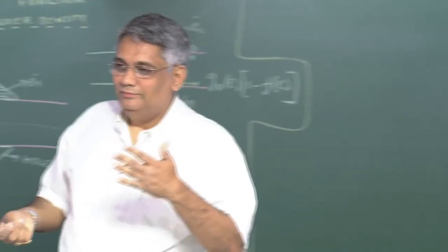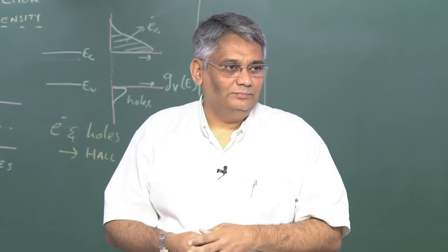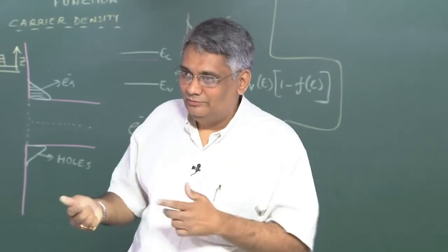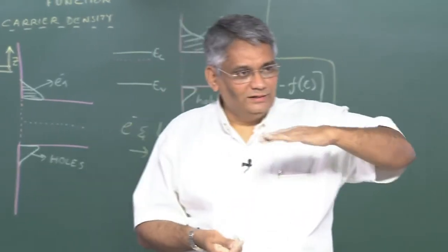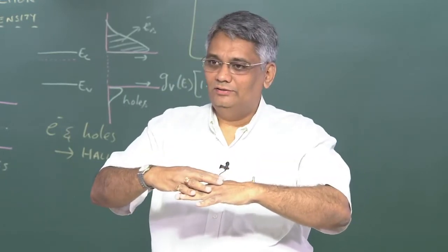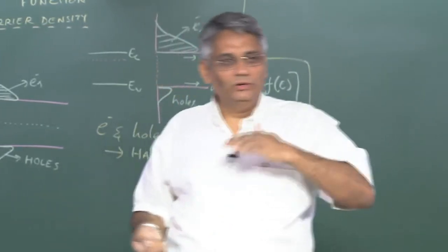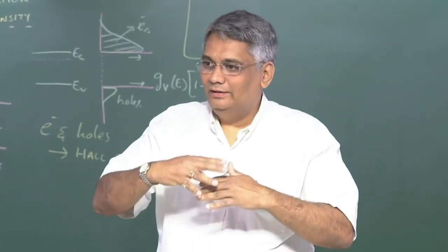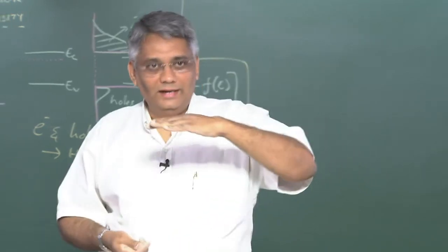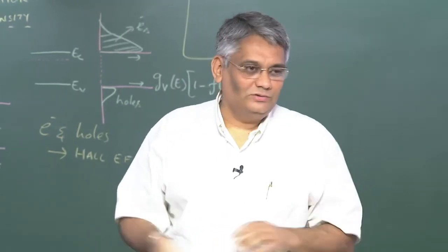Because if I have gallium arsenide, two layers of gallium arsenide, one is p type and one is n type, I can call it a homoepitaxial structure. Epitaxy corresponds to the crystallinity of the layers. A highly single crystalline layer of n type gallium arsenide and the single crystalline layer of p type gallium arsenide, I call it a homoepitaxial layer. But if I am getting two different layers, gallium arsenide and aluminum gallium arsenide, you can call it a heterostructure. If I am depositing gallium arsenide as one layer and say gallium nitride as another layer, it's a heterostructure.